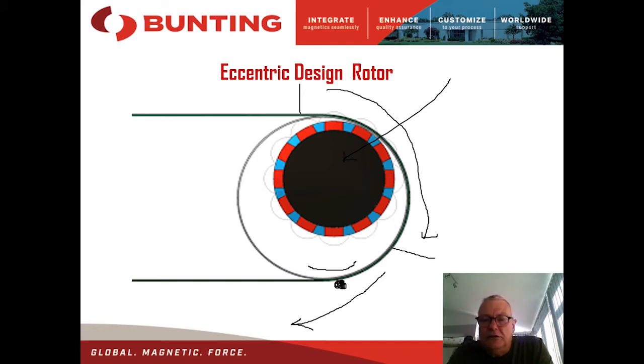Some of the disadvantages of it are that because this is a narrower pulley structure, the belt width, the effective width for practical manufacture, is less for an eccentric eddy current than a concentric eddy current. Concentrics can be manufactured to wider belt widths, hence higher capacity units. So for some clients it makes much more sense to have a concentric unit because they need 2 meter wide belts, and you can't do that with an eccentric, simply because it's a narrower belt, narrow pulley system, which creates more flex, which means it's less stable, so you can't run at greater widths.